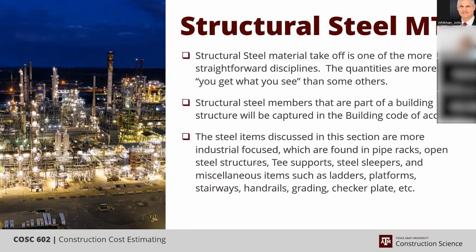and you know that together you shouldn't have a short fee, but you don't know the exact sequence of construction. At the end of the day, this initial schedule might schedule them all to be poured together so that there's no short fee. But for some reason, 4 of them or 3 of them didn't get poured and had to be postponed, and you have to order a short load later to finish it. Or maybe there's enough that you have 3 full trucks and then you have half a truck, and you're probably going to get hit with a short fee anyway.